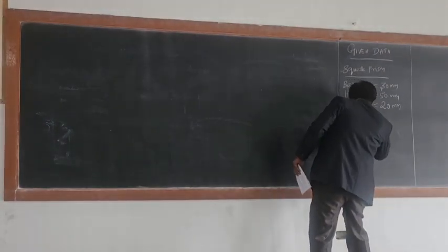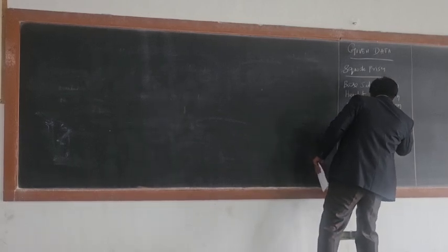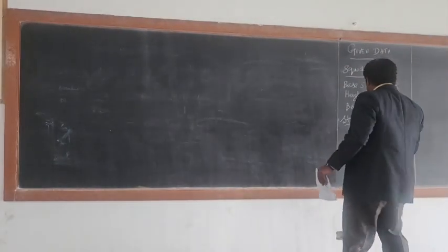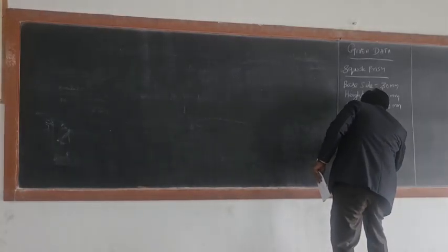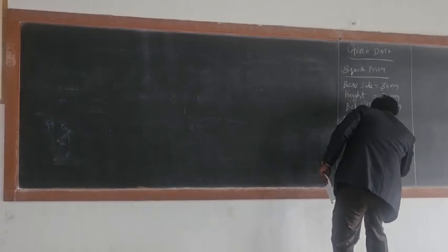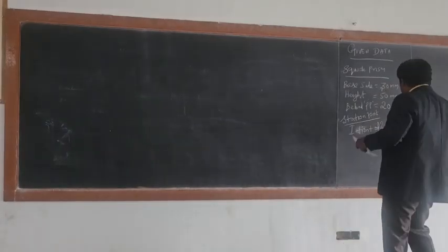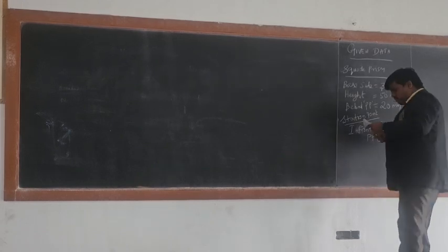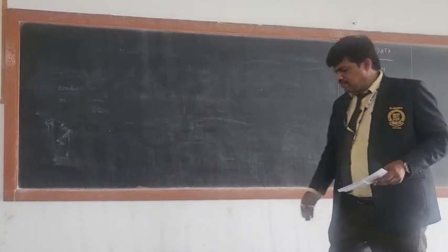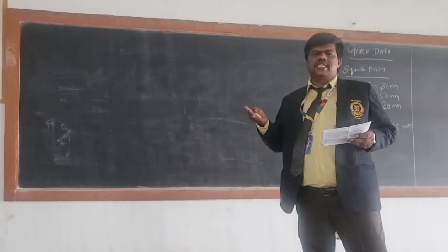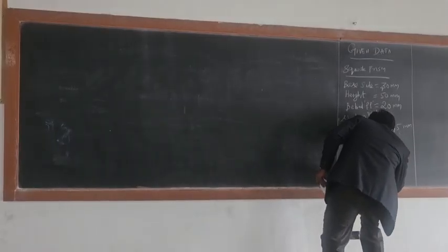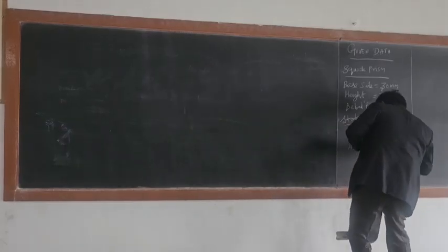Station point means the eye. So the eye is in front of the fixed plane, 45 mm, and 60 mm above the ground plane. This is called the ground plane.